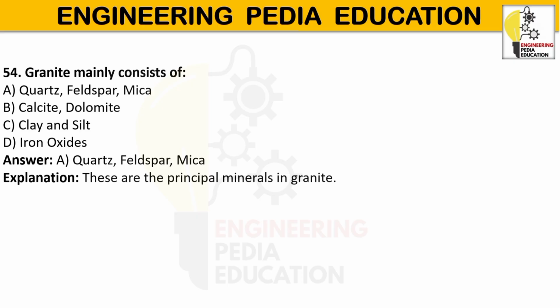Granite is an igneous rock, formed by slow cooling of magma below the surface. Its color is grey, pink, red, black, or white. Very hard and durable, with high compressive strength, low water absorption, and resistance to weathering and abrasion. It takes good polish, with no stratification and no cleavage. It is used as building stone, in flooring and wall cladding, bridges, dams, foundations, monuments, memorials, and road aggregates.